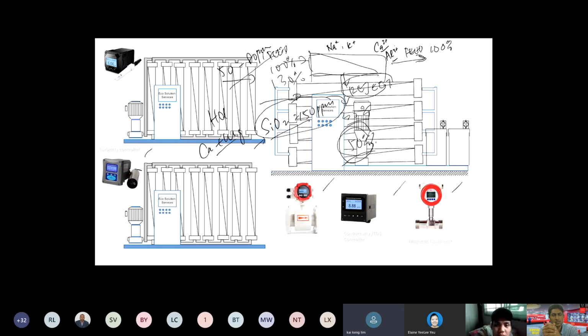So that's why just now we were talking about how much we're going to reject. It actually depends on how much alien mineral is going into our RO system. Then the amount of brine that we have to reject away has to be bigger. We have to turn a bigger valve to have a higher discharge of this brine to discharge it away.